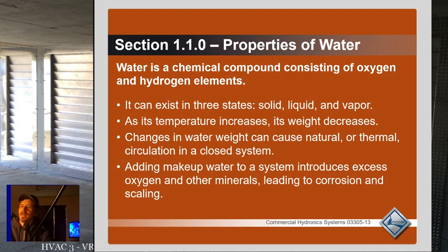You can design a hydronic system probably so that it doesn't even need a pump. Even when a hydronic pump fails on a boiler system, especially in like a house, when the boiler's on the first floor, a lot of times they'll still get heat from it because the warm water will tend to rise, the cooler water will tend to fall, and they'll still get some amount of heat performance out of that. So until they have a pretty cold day, they won't realize that their circulator pump has failed. That's not uncommon.